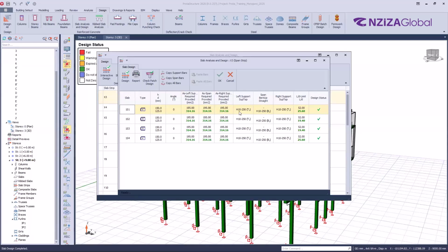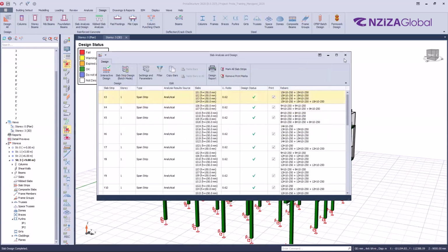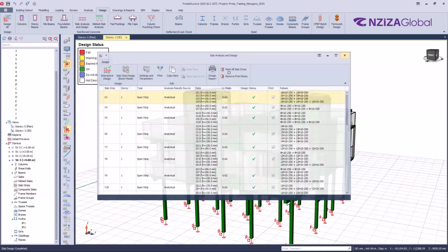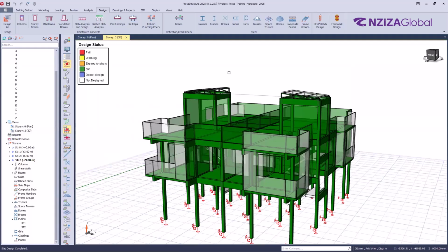So to increase the reinforcement in the slab, if you click on this reinforcement, for instance, you see you have these arrows to increase the diameter or the spacing. So it is failing on the reinforcement, now you use this. If it is failing in deflection, now you have to increase the height of the slab.